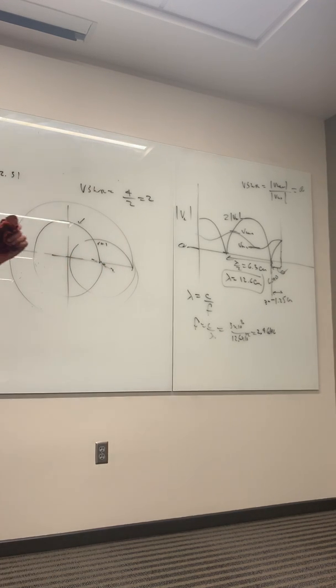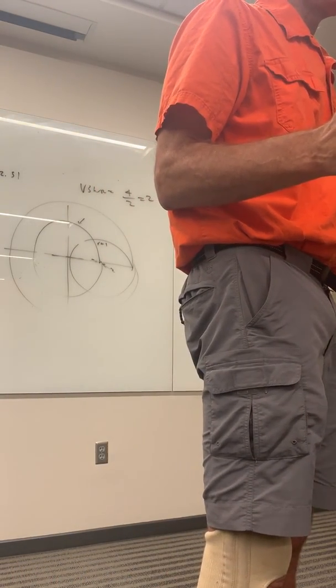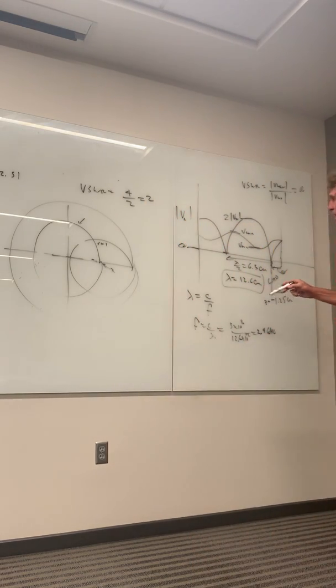Now he asks, what else? The load impedance. So this is Vmin here, right? I'm going to try to do this right. This gives me the position of the load, correct, class? And then I'm going to replace the short with the load.